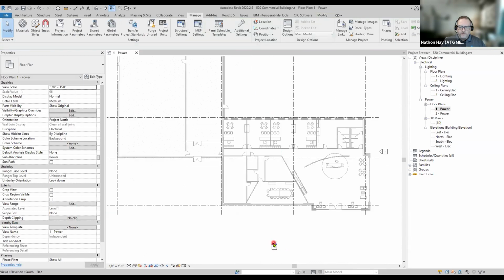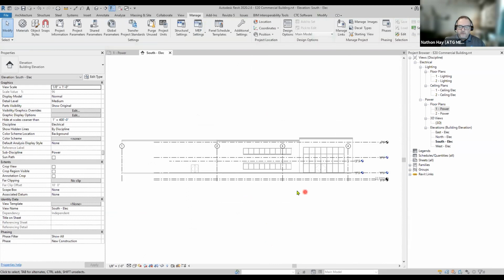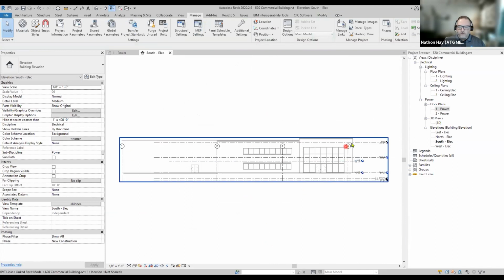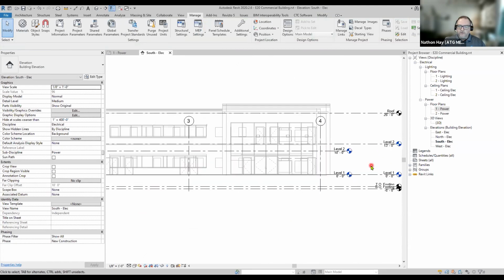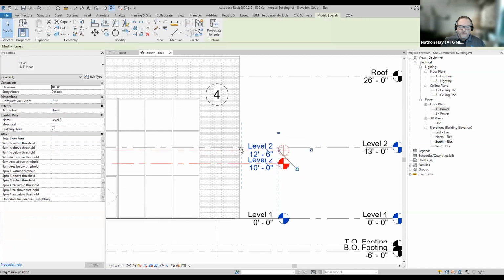So we're going to open up this one that's looking at this side of the wall. I'll just double click on the triangle. So now we're looking at the front of the wall of the building. You can see their windows and doors and all these levels. So we zoom in over here and we see our level 1, and I can't really touch their other levels. Here's our level 2. And I'm going to turn off that red dot. That's really annoying actually. I'll use this circle thing. So our level 2 needs to match their level 2. So I'm just going to click and drag it up.